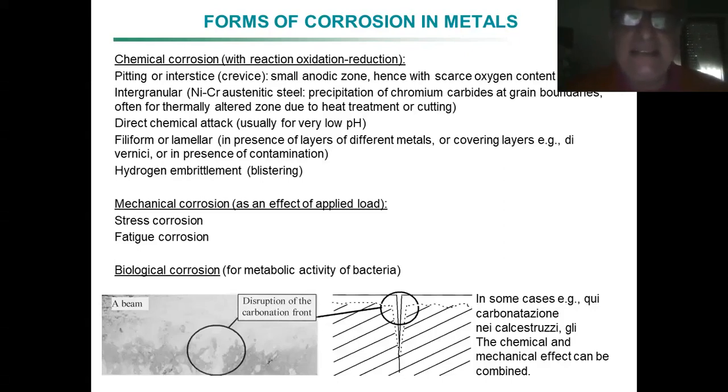These areas can be subject to crevice corrosion, corrosion into interstices. Because they get dirty, they might be attacked by chemicals, and be damaged with the formation of not pits, but crevices which are more extended in length. Pits are really points.